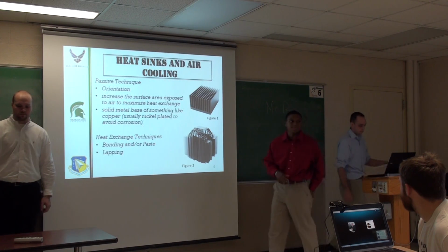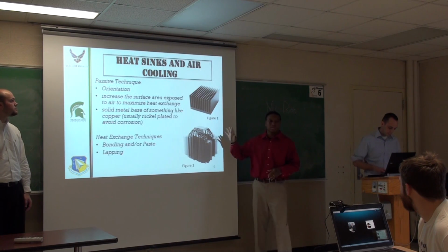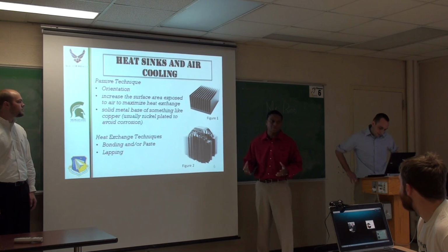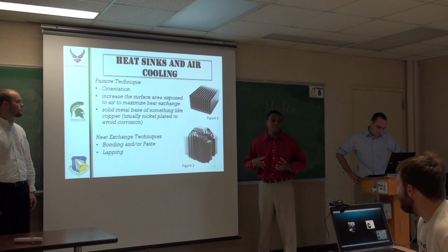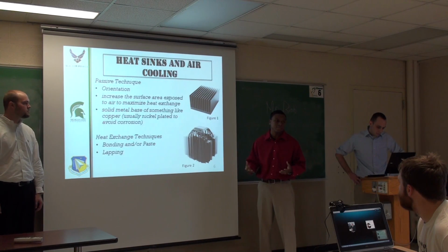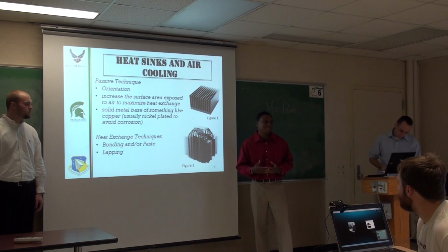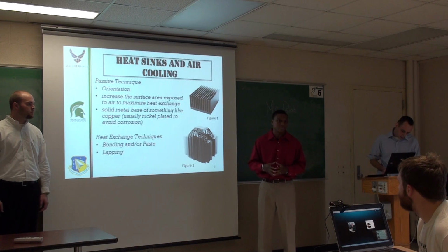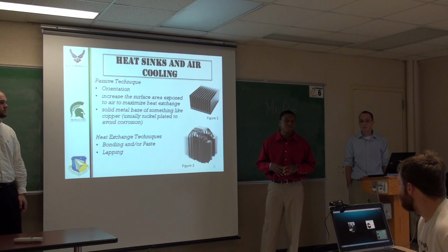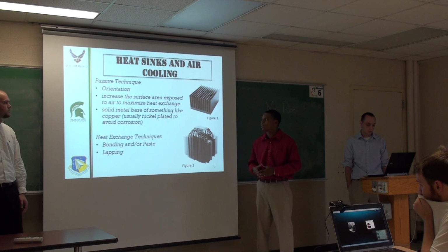Good morning again, class. My name is Cerrone, and I'm going to be going over heat sinks and air cooling. So the first technique of heat sinks, I'm going to be talking about the passive design. With the passive design, the orientation is very important, and that's because the heat sink has to have a physical contact with the heat source in order for the conducting of heat to take place. Also, the whole idea, the design behind the heat sink, is increasing the surface area. When you increase the surface area and you do a metal contact with the heat source, you're going to be able to conduct the heat through that metal more efficiently or more effectively.